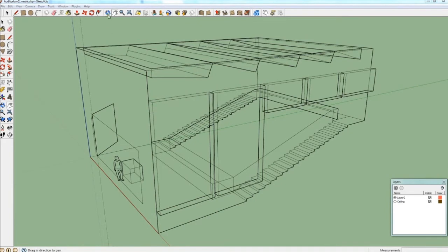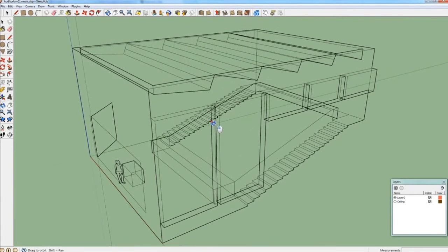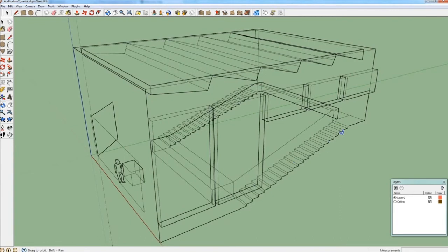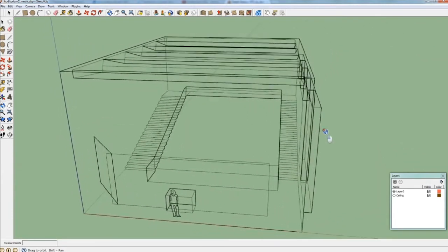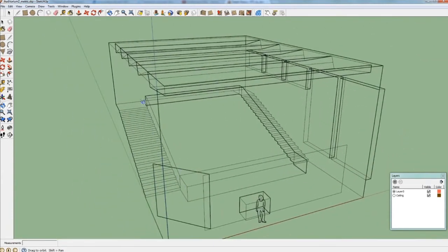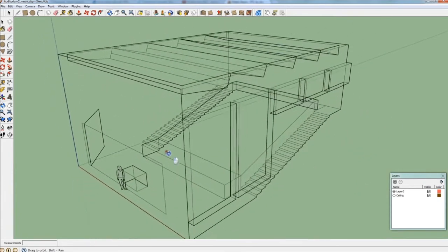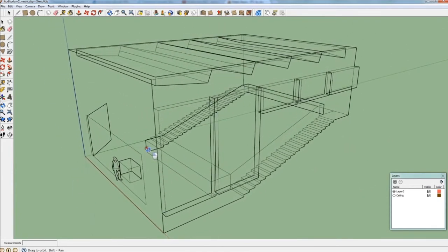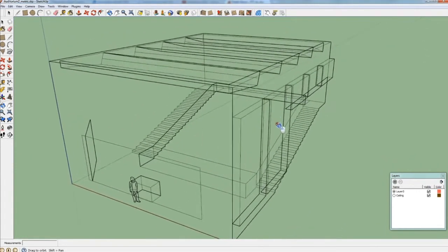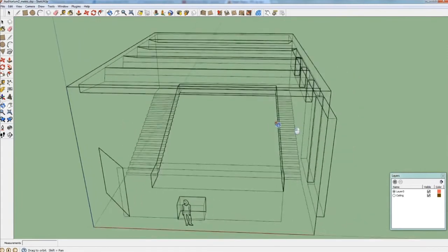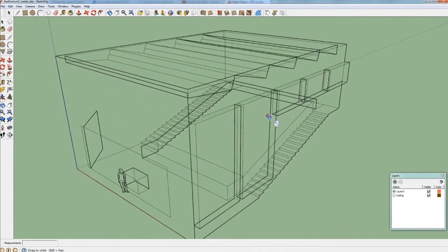Again, I want to show you in which step we are. So we have designed the stairs of the auditorium, and now we are going to model the audience area. And in general, it's good to remember that it's better to model the audience area as a box-like shape, as I have done here, instead of modeling the people and the seats individually. The reason for that is that many small surfaces, as the people are, introduce prominent diffraction phenomena around them.